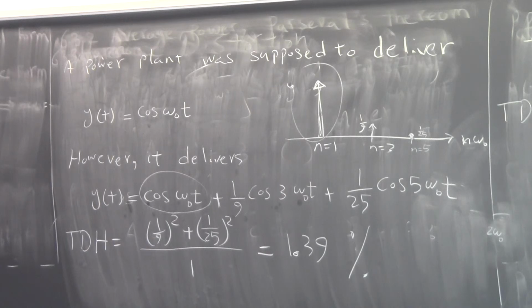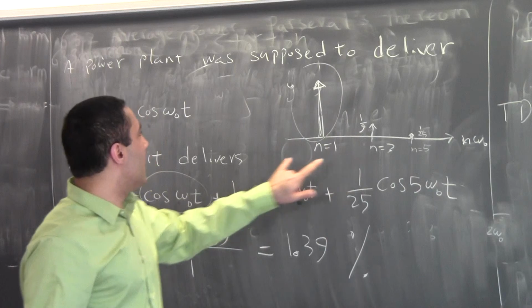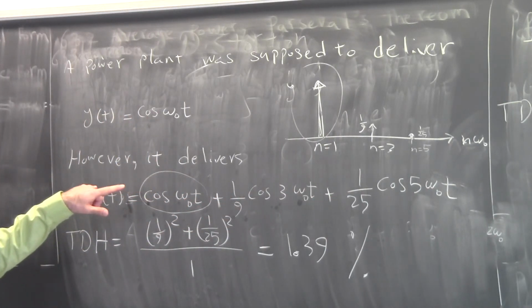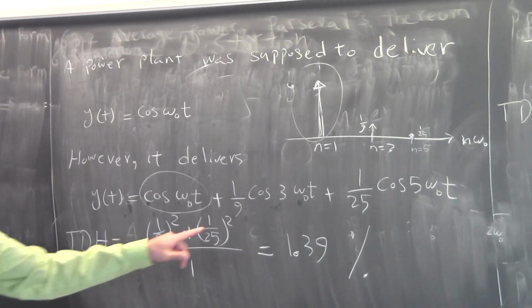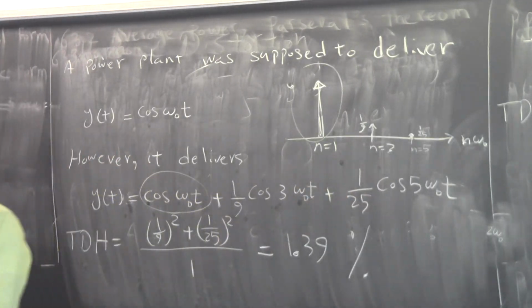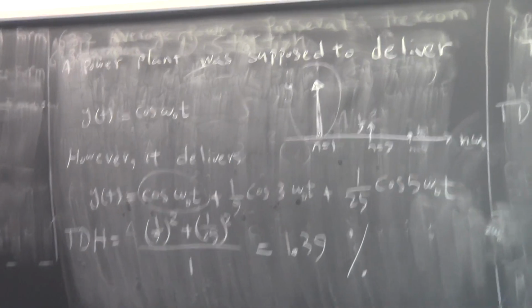So, any question? How would you deal with that in real life? If you don't like them, how do you deal with it? One way is to kill them by trying to minimize the nonlinearity in your system. Look for the nonlinear components and see where the root of the nonlinearity is. But I promise you, it's very difficult to kill them all. But one way is to just remove them from propagating inside your system.